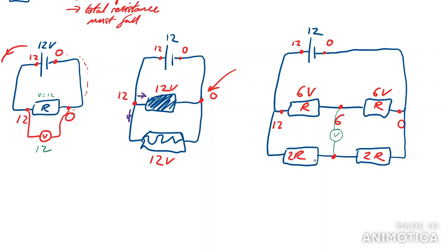Well, this is already the kind of question that starts to confuse people quite a bit in terms of solving it. But with this approach, you should see that it's very easy, because we know that the electron at this point had 12 units of energy, and then it chose to go down either that path or that path. So we've done the top path, that's fine. And so doing the bottom path, well, we know it's still got 12 units of energy left because it hasn't spent any yet. And we know it's got 0 when it gets to here, because it's not got a chance to spend any before it finishes. And these components are the same, so it must spend 6 across this guy and 6 across this guy. I mean, it's got 6 left here.